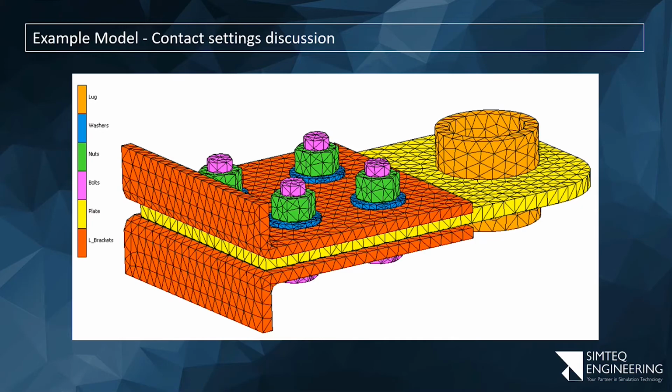Okay. So the assumption for this joint would then be, due to that load, if I preload this and I pull on this, the load will go from this side through the bolt, through the nut, through the washer into this, and is in friction being transferred. But if for whatever reason it slips enough so that that can make contact, you have to have that in. Okay, and then thanks, Gerrit.